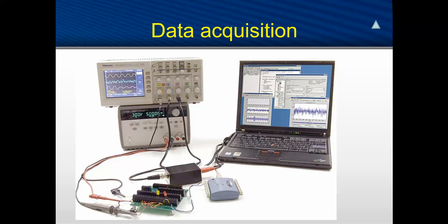The data acquisition toolbox in Matlab can support many hardware boards such as Raspberry Pi or Arduino boards. It depends on you what type of board you want to use. You can upload and download data, send data to the hardware board, and get the data to analyze using the Matlab program.